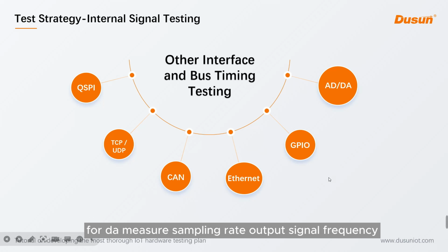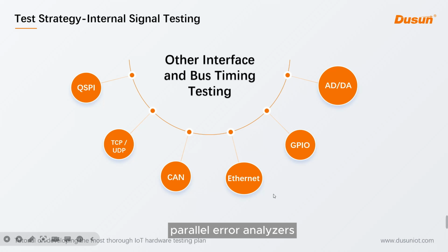For DA, measure sampling rate, output signal frequency, output signal power, and spurious free dynamic range. Use measurement instruments such as parallel error analyzers, multimeters, oscilloscopes, spectrum analyzers, power supplies, and software like DAC testing software.